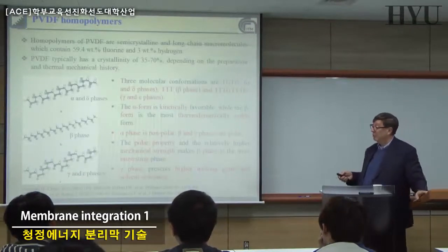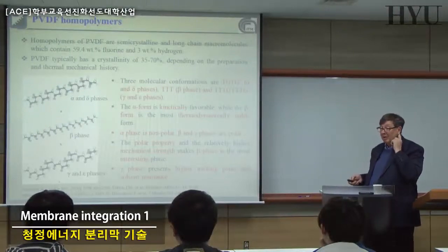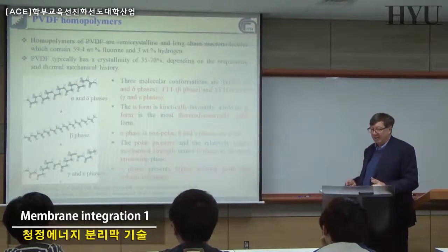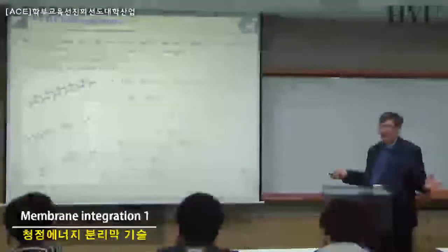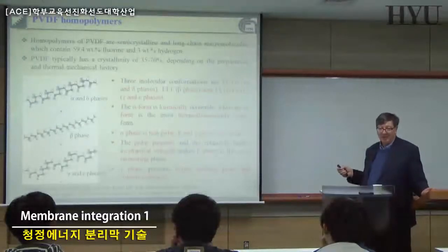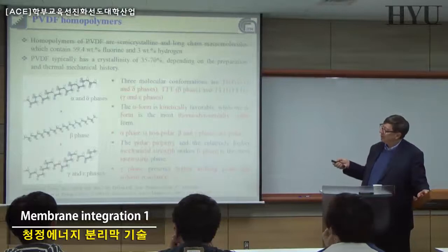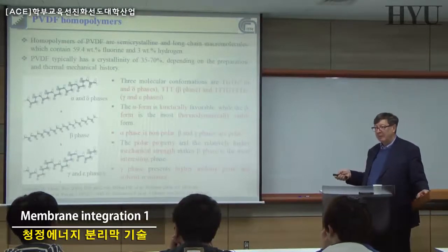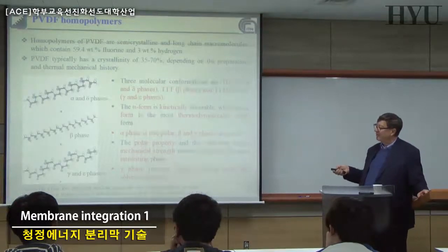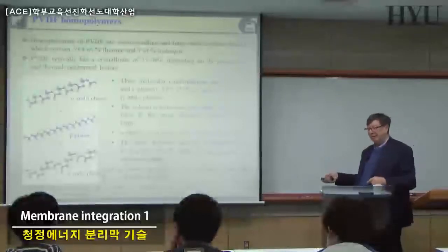Probably Professor Yamoli already mentioned that you also have to start to understand more what you really have in your hands. For example, everybody is working on PVDF. Now, some of you are aware that PVDF is not just PVDF. There are hundreds of different kinds of PVDF. PVDF exists in different polymorphs, and each one has different properties. Some of them are polar, some are non-polar. Some of them are piezoelectric, some of them are non-piezoelectric.